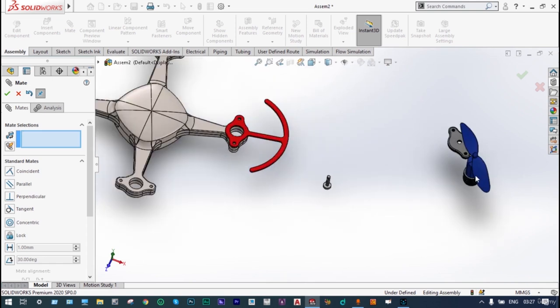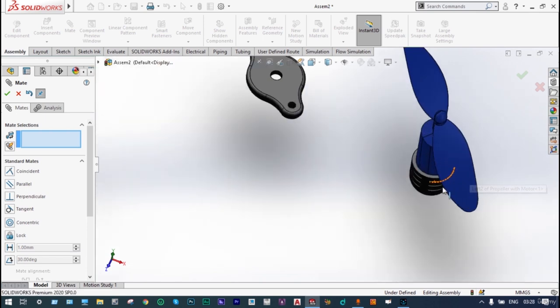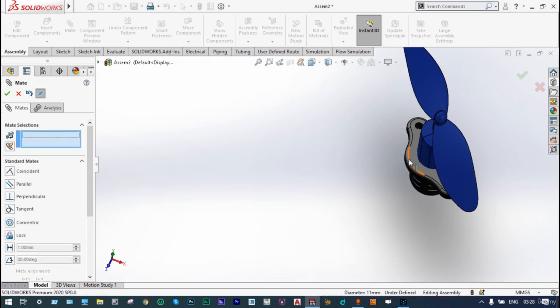Next to that, we have to meet this motor and this radiator together with this flange. Okay. So the circular portion of this one should be met with circular portion of this one. 1 constraint is met. Green check. Now the second one also required.